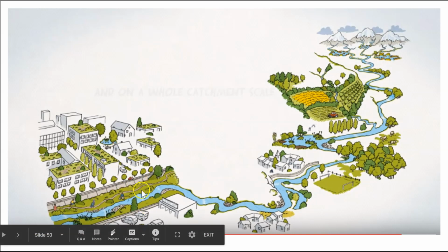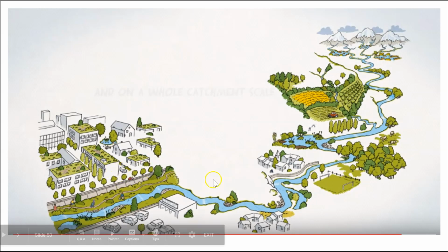And if you're going to use the hard engineering there because you've got the high value land nearby, then are there ways that you can soften it slightly? Can you set the flood walls back a little bit? Create just a little bit of space around the river, create habitat diversity there, allow for a little bit of the storage capacity of the floodplain in this area. Can you soften down those hard engineering bits a little bit here?